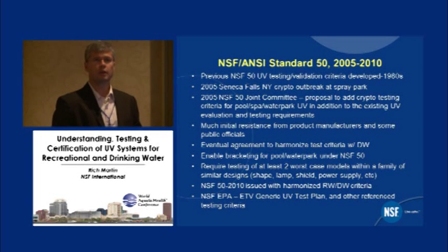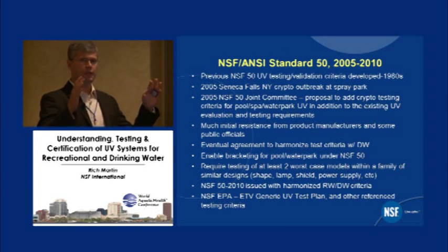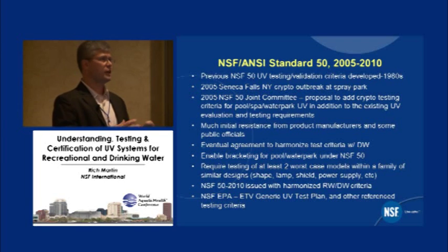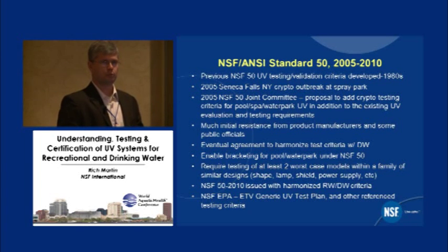And so the focus was really on some of those highest risk facilities or applications of water, the spray parks and spray pads, because of the propensity for volatilization or spraying of the water, and that really kind of knocks out a lot of that residual halogenation disinfectant. And so you're looking for a way to treat crypto, which we all know is so chlorine resistant. So there was another method that was pursued.